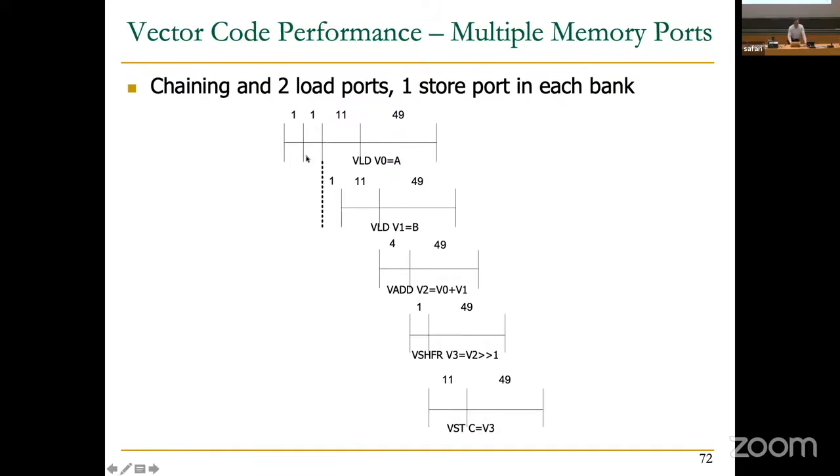And this will enable us perfect pipelining right now. So basically you start the first load in cycle 1. The second load is completely independent of the first load. It can go to the other load port. So you start the next load. So basically you almost completely overlap the latency of these 2 loads because they access 2 different ports in memory. Of course, 2 different ports is expensive, right? Clearly. 2 different ports is really 2 different address buses and 2 different data buses. But then, of course, it's shared across banks. But still, it's expensive. But you could parallelize.